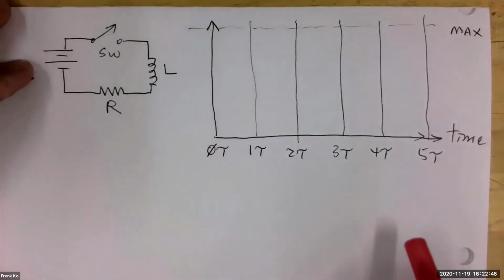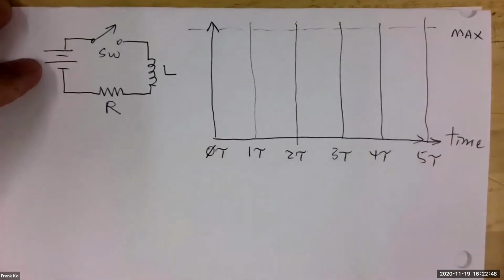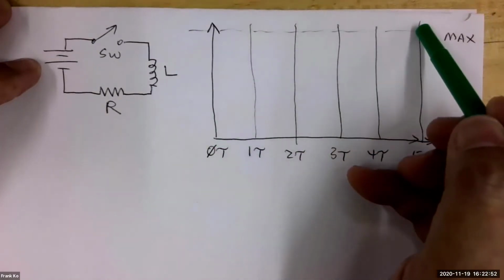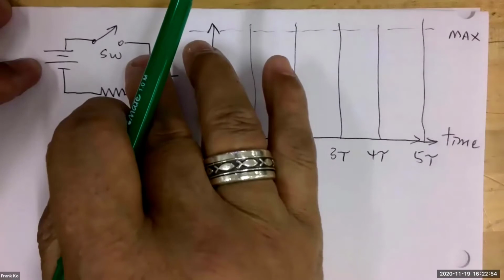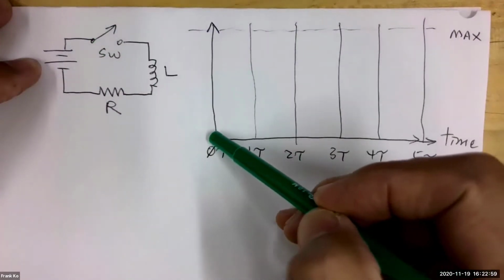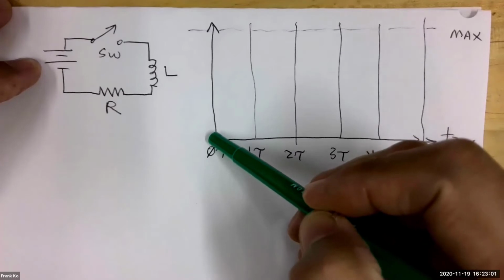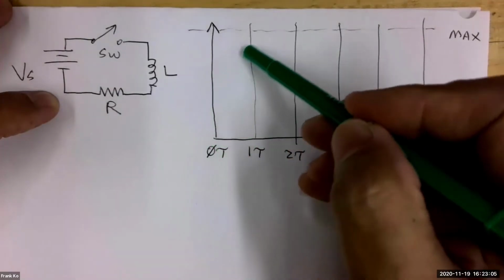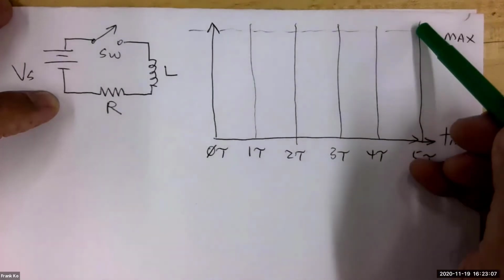Well, if you remember, the capacitor voltage took a while to charge up to maximum. If it was a capacitor that we discussed a couple weeks ago, the moment we close the switch, the voltage on the capacitor starts off as nothing, but after 5 time constants, the voltage on the capacitor goes all the way up.